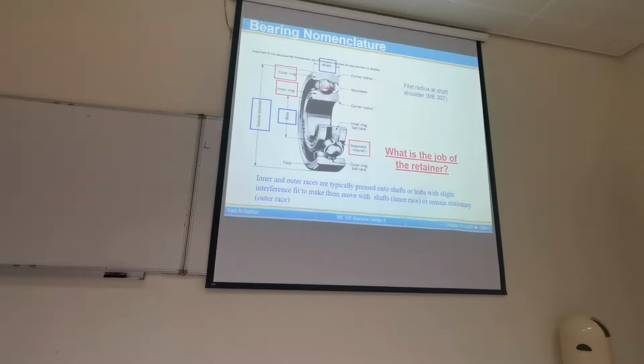Every time your modulus of elasticity increases, it means the rigidity of the structure increases. You need more force to cause deformation. And every time the size increases, it also becomes harder to deflect. Now, one other way is to increase support. If I have large deflection, adding more support will minimize this deflection. So increasing the width of the bearing is one way of increasing rigidity.